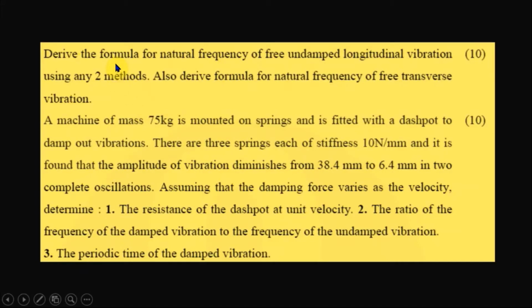We will discuss these questions from previous KTU examination on dynamics of machinery. The first question: derive the formula for natural frequency of free undamped longitudinal vibration using any two methods. You can make use of Newton's equilibrium method, in which we establish a force balance, and the second method you can make use of energy method.